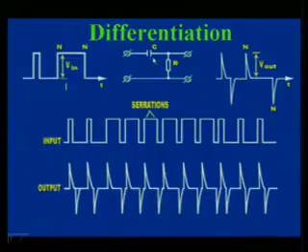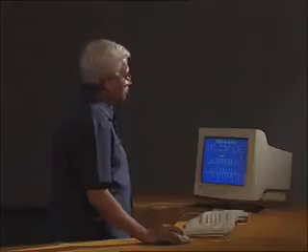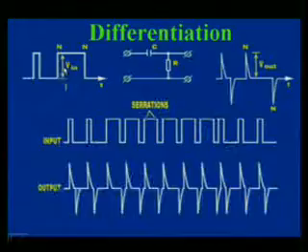This capacitor is of lower value and charges immediately when a long duration pulse comes, or even a pulse of shorter duration, but higher than 0.1 microsecond, the capacitor will charge.